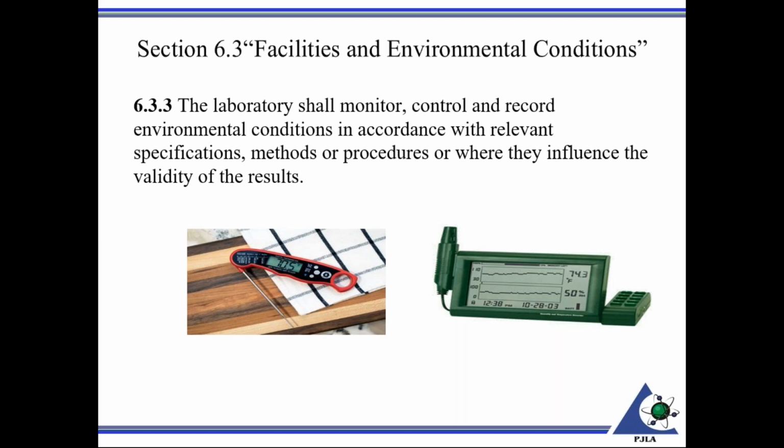You may have to capture it real time as you're doing the test or calibration, or perhaps you need to monitor it more thoroughly to assure that the environment was stable prior to when the test or calibration. So in those instances, perhaps a data logger, which is pictured over to the right, to assure that there was no drastic changes in temperature or humidity, in particular example over there on the right, that could possibly impact the unit under test and impact the test or calibrations that are being performed.